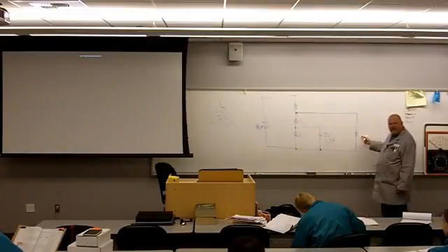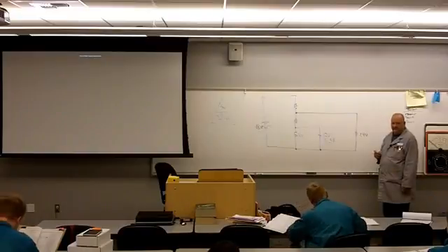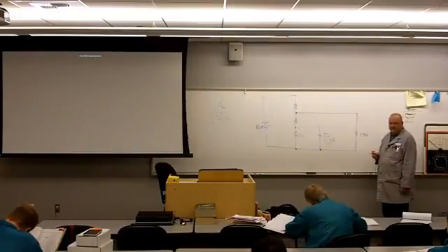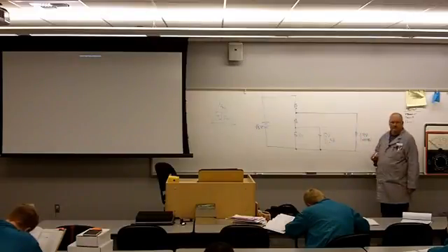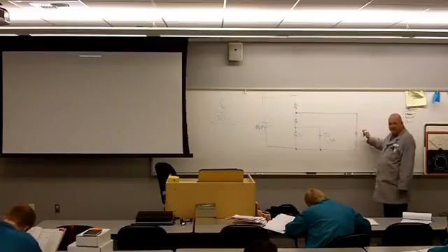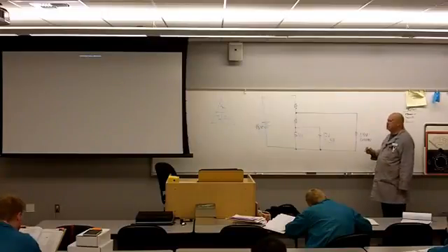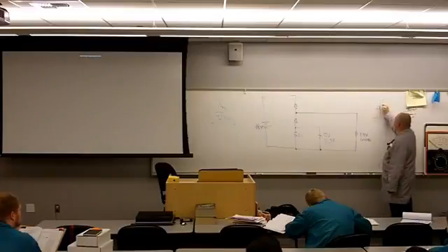The voltage of my commercial radar system is 24 volts DC, and it puts out 200 watts. How much current is going to be needed to go through this device in order for it to transmit out 200 watts? Again, if you get confused, draw the triangle, PIV,